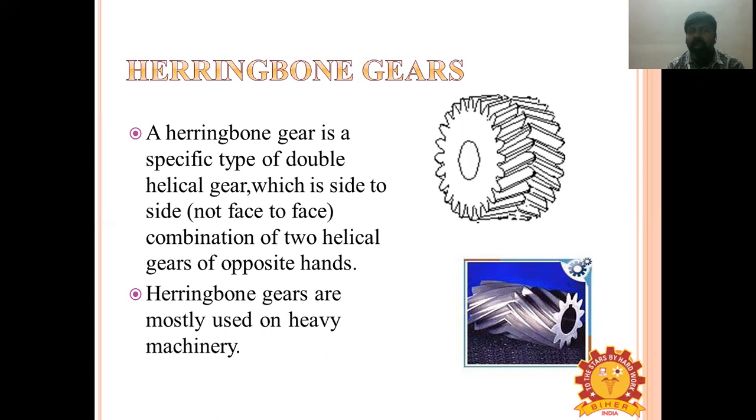Here also we have a helix angle. Helix angles are usually greater for herringbone gears than for single helical gears because of the absence of thrust reactions. So herringbone gears are preferred.